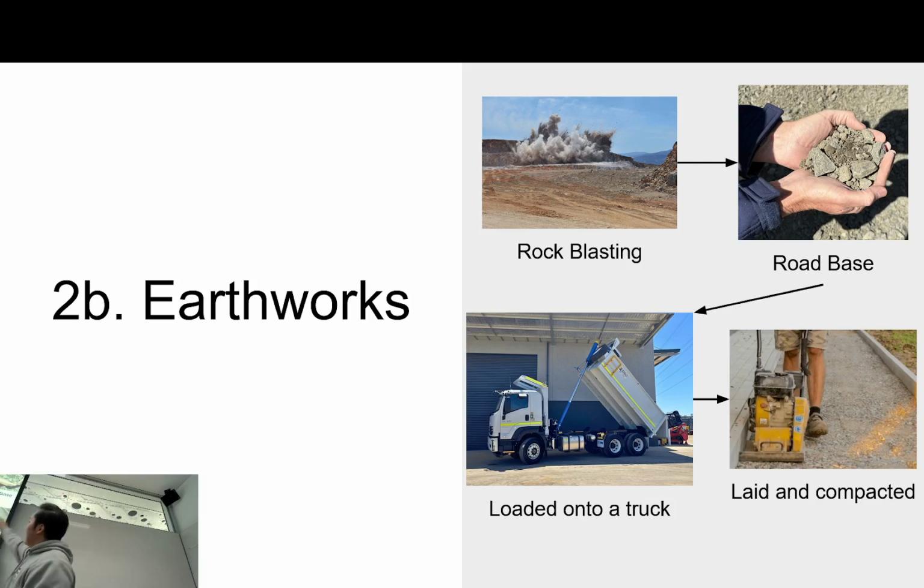Now, when you lay down that road base, right, it will have a lot of what we call voids. So it will have a lot of empty space in between the rocks. You can imagine the rocks don't tessellate very well, right? So that's why after we lay it, we have to compact it as well. This is a compactor, and basically you just put it around and it vibrates and it settles all that rock into a nice compact even layer. So when you walk on it after, you won't be able to kick up the rocks. It'll be pretty solid and firm.